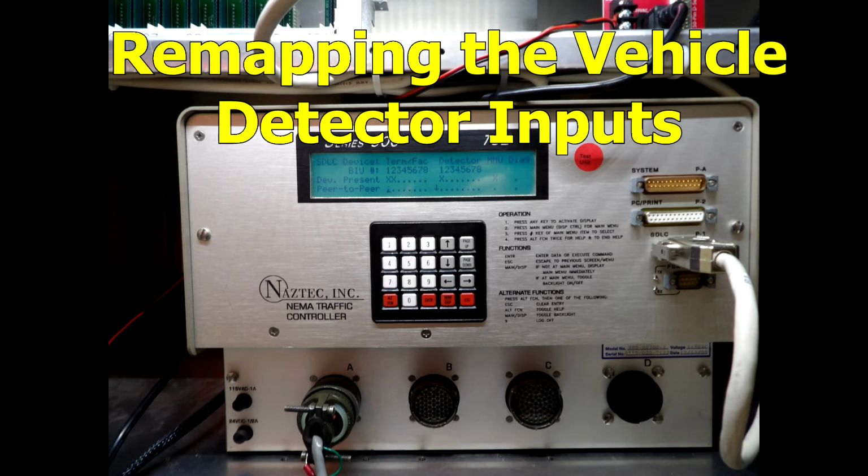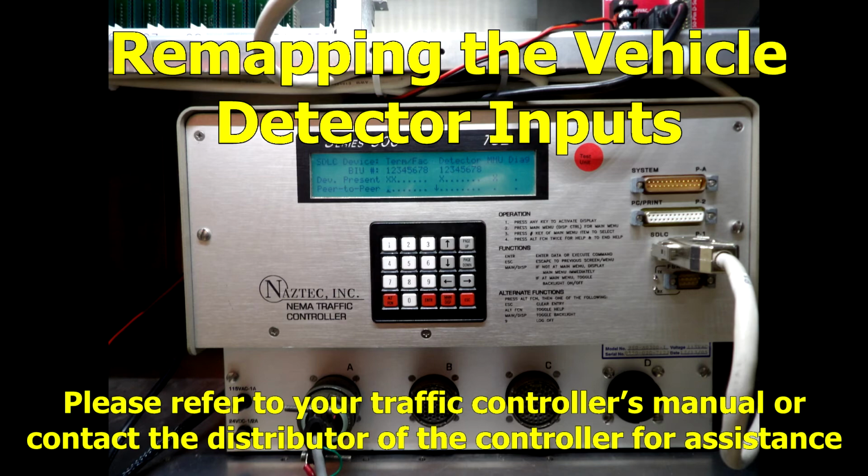Remapping the vehicle detector inputs. You will need to remap the controller vehicle detector inputs to PED inputs. Please refer to your traffic controller's manual or contact the distributor of the controller for assistance.